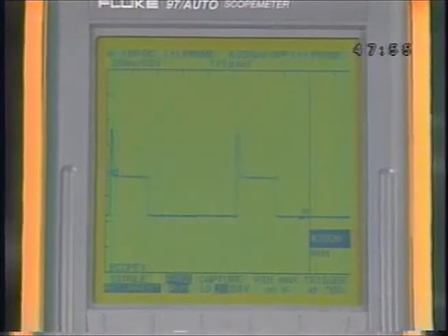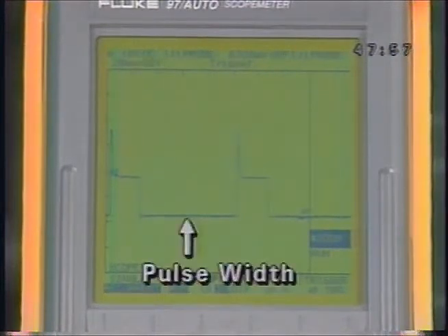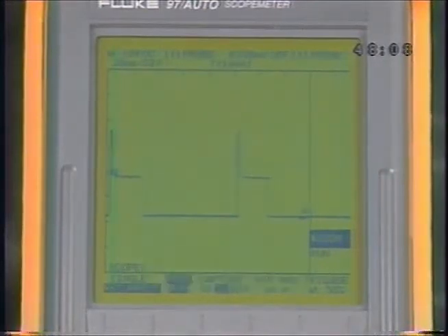Now, examine the waveform. Remember, dwell changes are nothing more than changes in pulse width. In closed loop, the computer responds to changes in the fuel mixture by varying the pulse width. The setup for this exercise will be useful in the shop for diagnostic procedures. Freeze the signal and save this setup to setup memory 2.